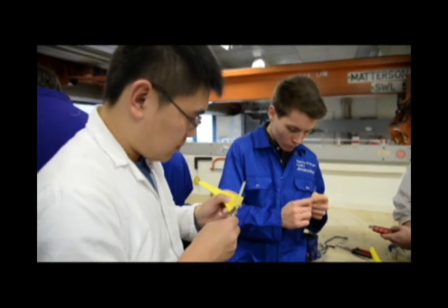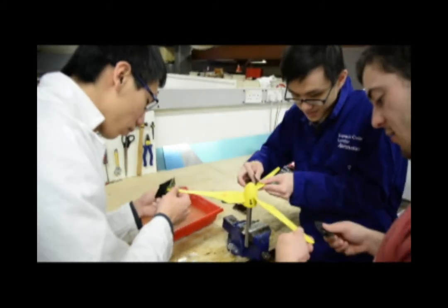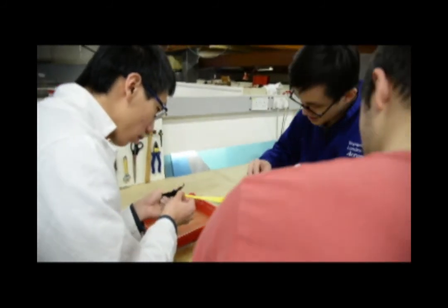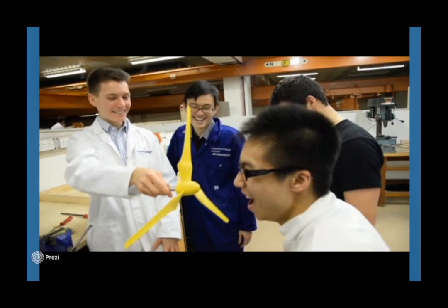The wind turbine was glued and allowed to settle for a day before sanding took place. In the design stage, the turbine was designed to be thicker than desired, and sanding is used to reduce the thickness to the required dimensions. The surface of the blade was also sanded to create a smooth surface and for better aerodynamics.